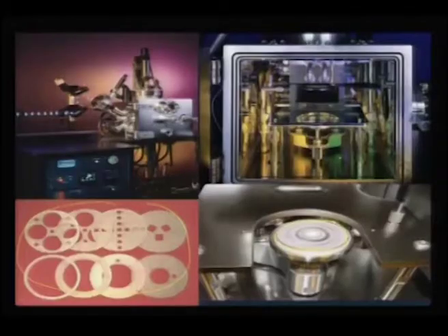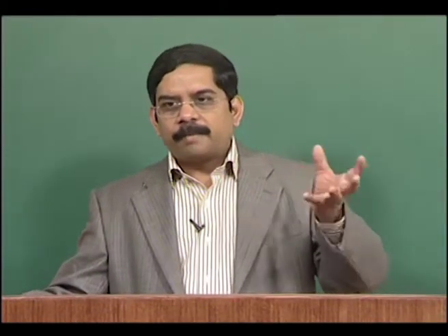So the inside part of the chamber essentially will look like this. You can see here these are the rotating wheels. Depending on the choice of material, you can keep switching between targets, and this is how the deposition chamber will look. This is another example of how PLD can be used for a superconductor, and you can see here several stackings of these superconductors can be made. This is YBCO, which is coated and then capped with ceria, then praseodymium cuprate, and then LaAlO3 as substrate. So this is a device configuration. All this can be achieved with the same chamber with a different target carousel. So if you have 6 or 7 targets mounted, you can realize such a complicated device stacking.